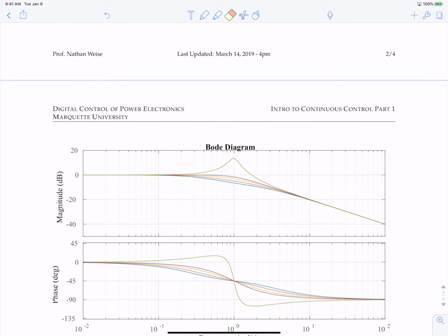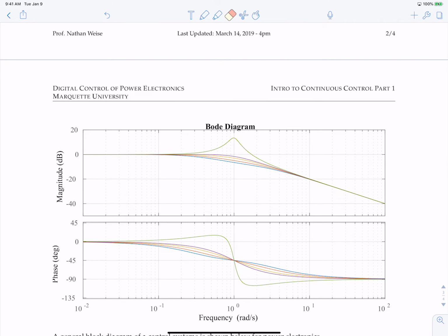It's underdamped, so you're going to get some ringing. And you get ringing at this frequency here, which turns out to be, in this case, the natural frequency, or the resonant frequency. Okay, so just by looking at the Bode plot in terms of gain, we can say, oh, these are nicely damped. These first 4 are pretty well damped, pretty well behaved. But this last one, we can tell just by looking at the Bode plot, we're going to have some ringing in any type of response. So you can correlate all these different ways of looking at this to understand what type of response you have and how you can push your system to deliver the type of response that you would like.